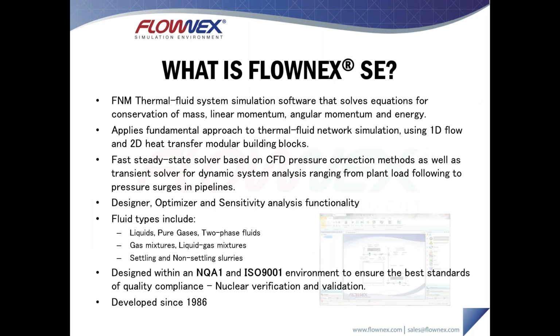All right, so Flownex itself is what we would call a flow network modeling systems simulation software package. It sounds like a bit of a mouthful, but basically it is a one-dimensional network solving package. So it's software designed around one-dimensional flow elements and two-dimensional heat transfer elements, which you can use to build thermal fluid networks. This is then solved in a very similar way to CFD with governing equations or conservation equations for mass, energy, and momentum considered.